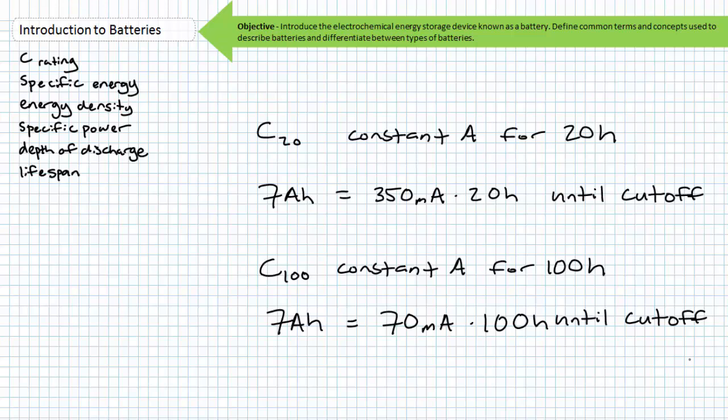This is to suggest that you must be aware of what standards the battery will be held to for a particular application. A UPS might only briefly require energy to ride out a momentary grid disturbance or initiate an orderly shutdown of an affected system, whereas a battery for a mission-critical off-grid application may have to ride out several days of no sun or wind before the next recharge. A battery with a nominal energy capacity expressed in terms of the C100 rating gives a false picture of that same battery's capacity when withdrawn more rapidly over the course of 20 hours.